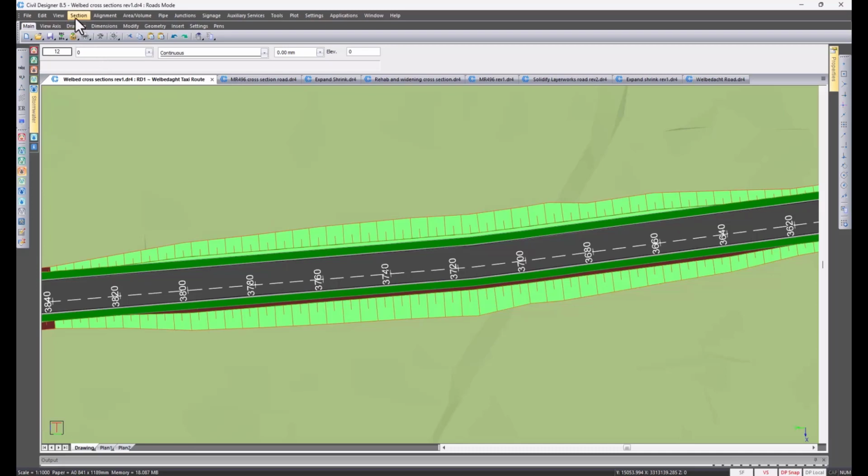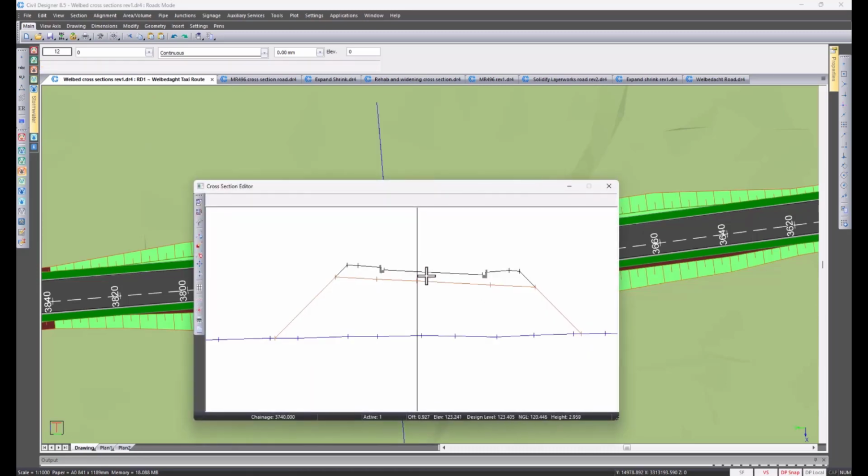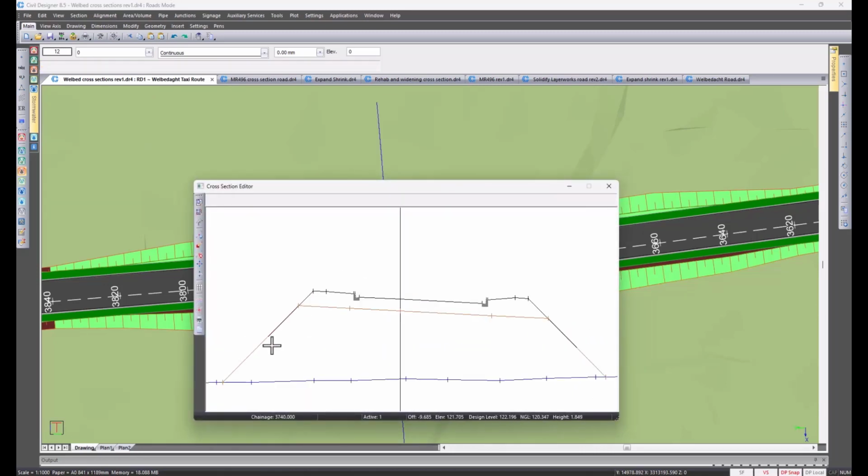So then it's section, graphical edit, select the chainage that I want to view. In this cross-section, you can see now that for the bottom pavement layer, we've created a totally separate cross-section, which is intersecting with the batters and runs across the remainder of the design cross-section, and then shows that depth of the bottom pavement layer below the final design layer.